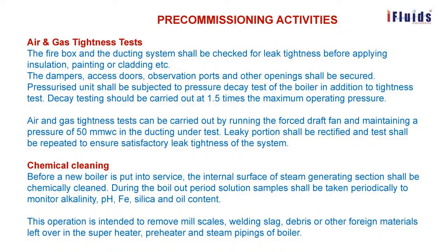So this liquid can be prepared and heated up to a temperature of 70 to 85 degrees Celsius. And the treating time required is 12 hours. So based on this, all the grease and other components or any slag particles are removed.